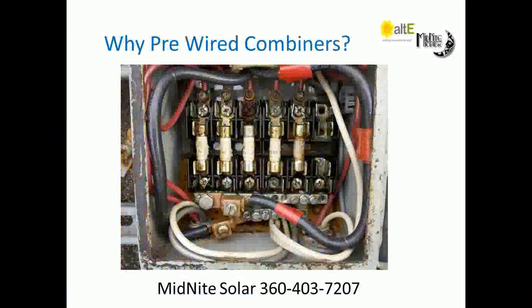So the SMA and the Xantrex XW frequency dither. The Magnum and the Outback do not. So if you're doing AC coupled and that's on your mind, those two frequency dither. The difference with the SMA is it goes a step farther, and if it's talking to a Sunny Boy, it can frequency dither in little bites, and it won't turn the inverter off. It will throttle it back just like a charge controller would, if you will. So if you've got a 6 kW grid tie Sunny Boy and you only need 4 kW to maintain the batteries, it will throttle it back down to 4 kW and maintain the batteries.